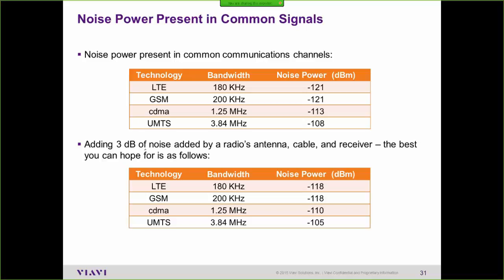Well, let me give you a quick example. I've got the analyzer up here and I'm running it, and I'm going to switch just to the spectrum display. Right now my RBW is set to 1 kilohertz. I don't know if you can see that or not.